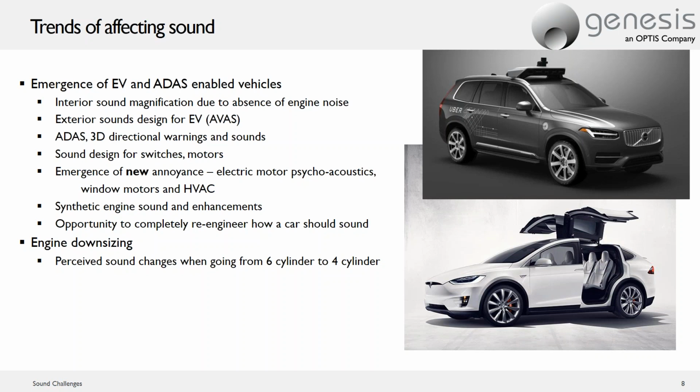So we can use this software to replicate an engine sound inside the cabin, not based on an RPM signal, because with an electric vehicle there is no RPM signal, but based off of the pedal position.